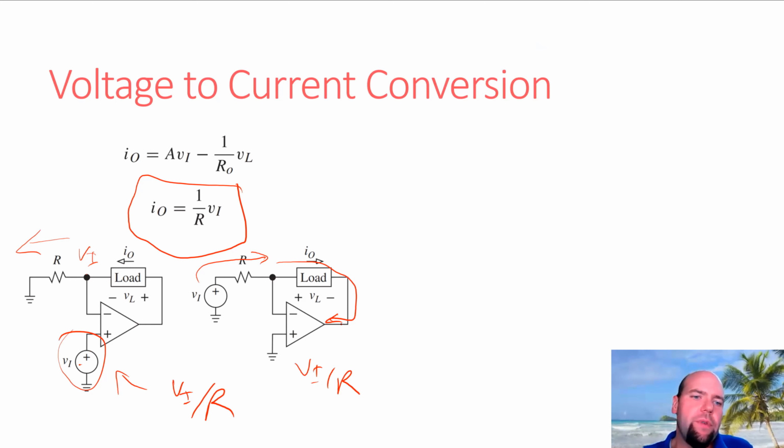So what about this? In this case, the op amp needs to produce a certain current in feedback to balance out these input terminals. And we're basically saying, just stick the load in the feedback path, and whatever current the op amp needed to produce is all going to flow through the load. Boom. We're done. What's not so great about this? You'll notice that this load is what we call a floating load. That is to say, neither terminal of this load is set to ground.